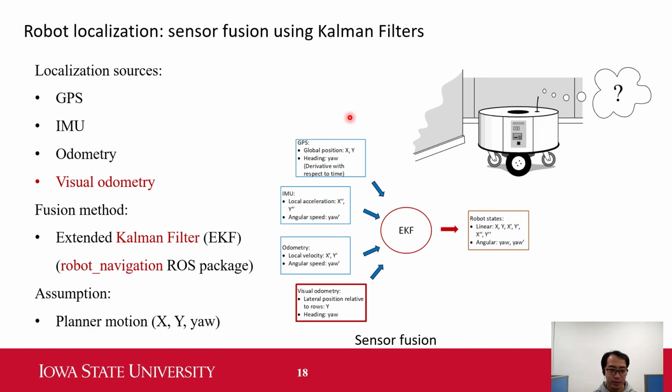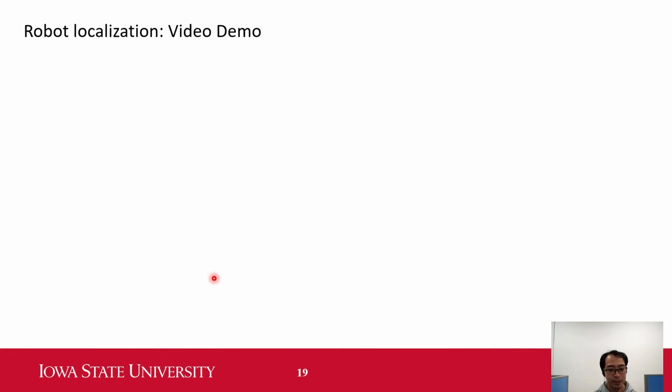The next module is robot localization. This tells the current position, heading, and the velocity of the robot. So fusing GPS, IMU, and odometry is a common strategy. Since we use a Kalman filter, we can directly use the robot localization package for this. After implementing control and localization, we could start a test in simulation to verify the performance for motion control.